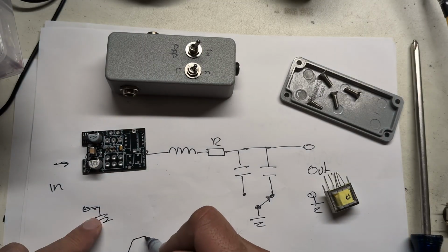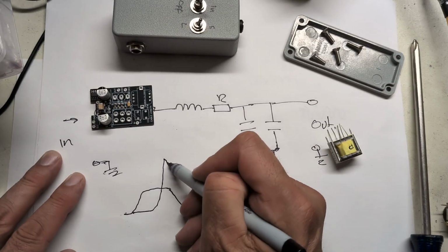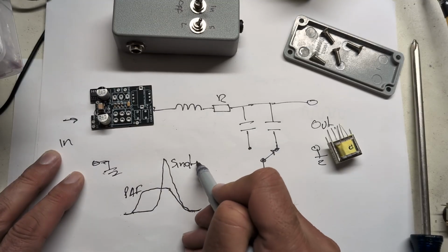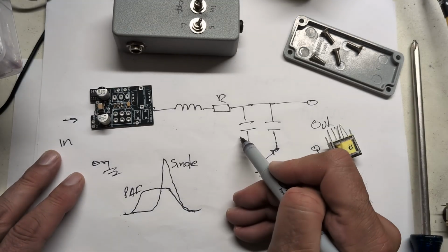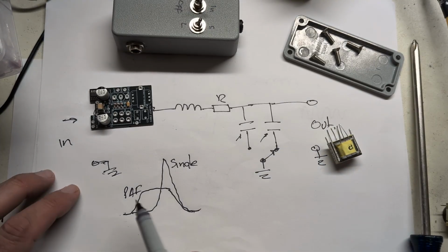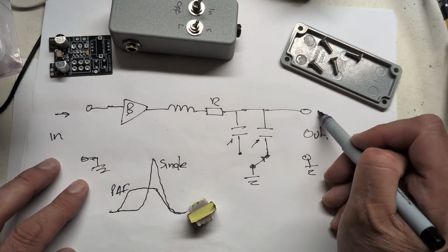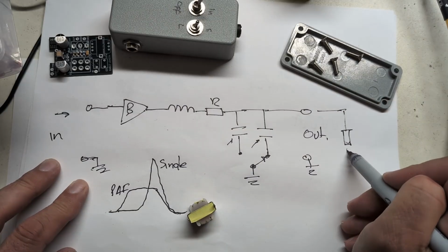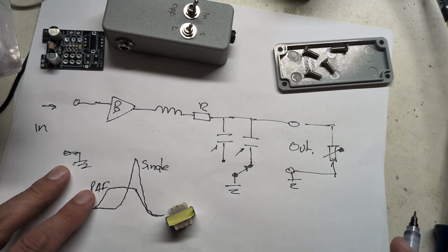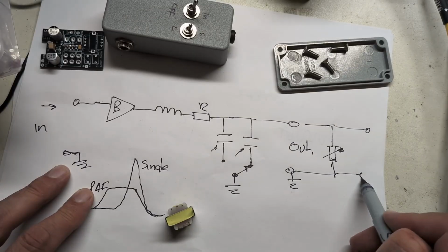for the pickup responses. So if we remember, our pickup has resonant frequencies that kind of look like this. So this is a humbucker, and this is a single coil. And so by messing with these capacitance values in the nanofarads, we can change the characteristics of the guitar signal that we're trying to emulate. And then this here would then go maybe to an expression pedal. So I'll put that in there. So we can use the pedal to emulate the guitar volume pot, and then this would go to the fuzz